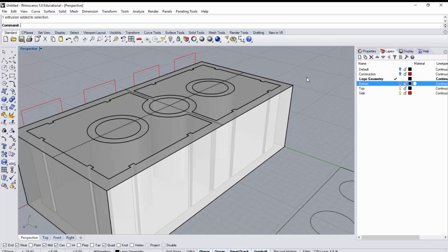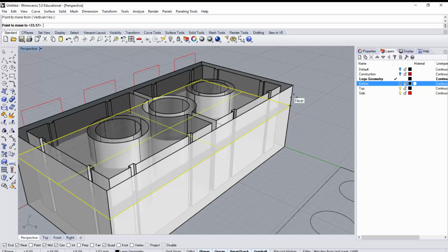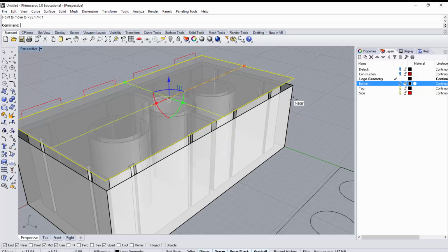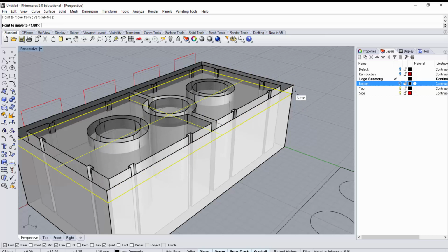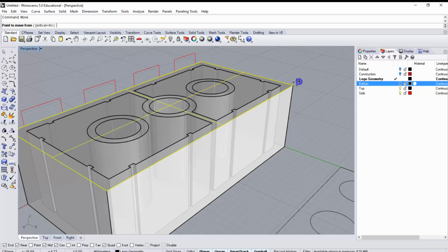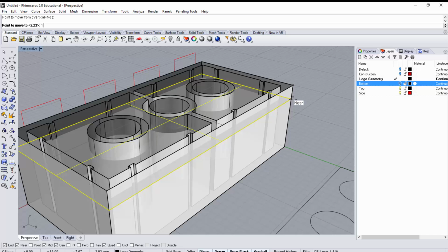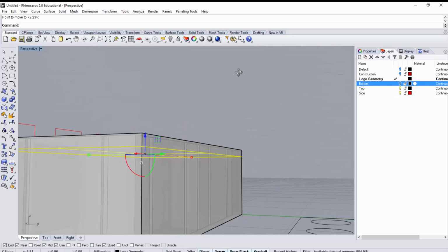I made two surfaces accidentally, so I'm going to grab one surface. I'm going to move it down 1 millimeter. So I'm going to say vertical yes. Grab the corner here, and I'm going to say 1. Didn't mean to do that. Let's step up, try it one more time. Move it down. Okay, that way. Sometimes it likes to just snap on and move it automatically. There we go. It's now down 1 millimeter.